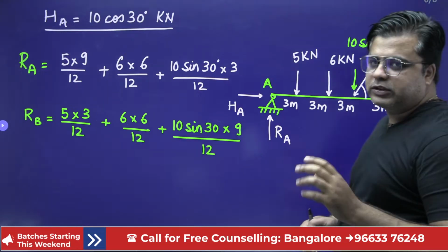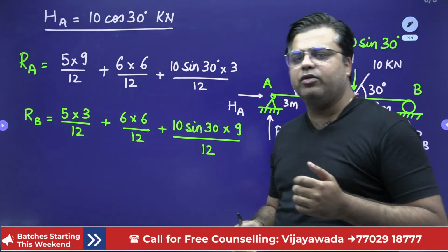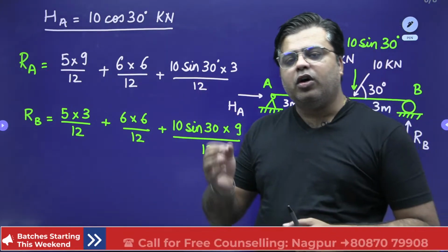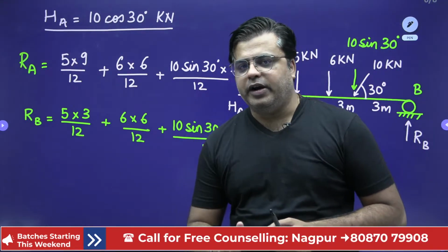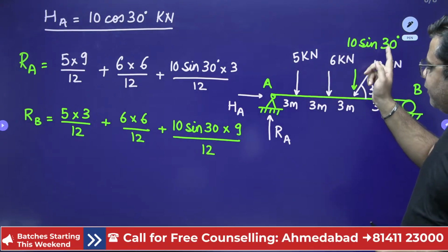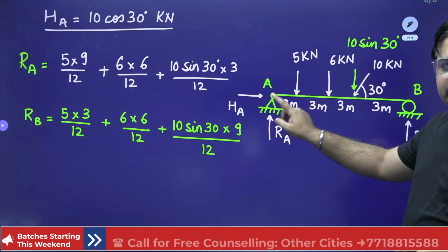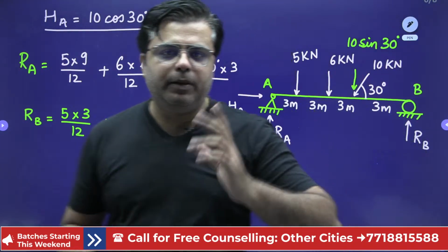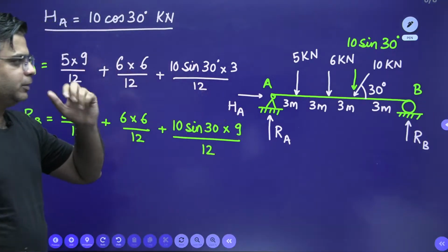We know that force is a vector quantity. So either you can understand it in terms of the principle of superposition, or in terms of components. That is, for every transverse load, there will be a component of RA and a component of RB. So this is how you can deal with complicated beams for calculating the support reactions.